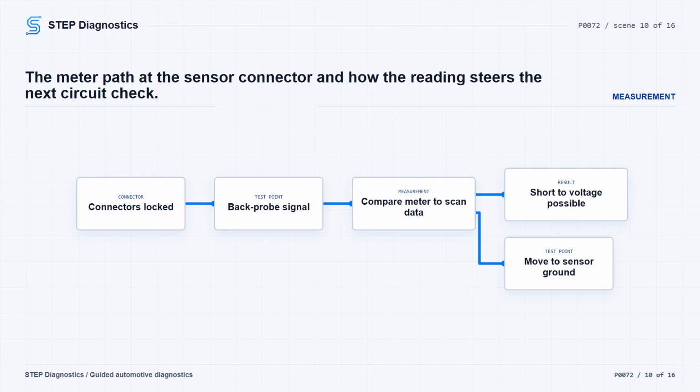If the signal circuit checks good, inspect all connectors in the system for pushed out, spread, corroded, or dirty terminals before condemning an ECU. If the DVOM result points you toward the sensor ground side, move the test lead and back probe the temp sensor ground circuit at the temp sensor harness connector.